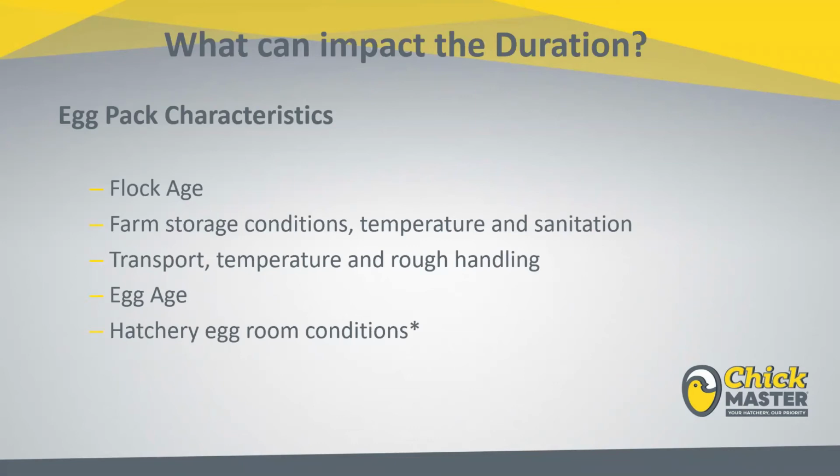And the next question, why we use an RH sensor in the setters and tend to veer on the wet bulb for the hatchers? Yeah, so if you'll remember back in the earlier part of the presentation, the real key around wet bulb is the simple fact that it is nothing more than a temperature sensor itself that is completely sealed probe, and by design will handle high pressure hot water wash down. It'll handle the fact that in a hatcher machine you have to wash it down a couple of times a week, and it's really rough on that probe.